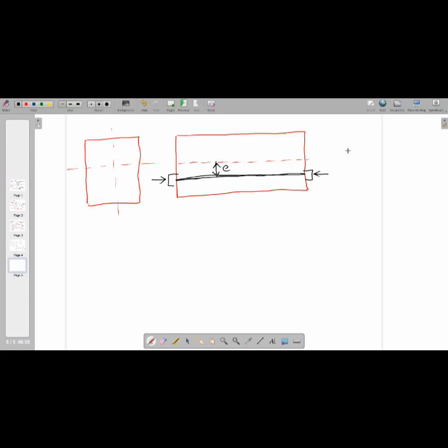Now see students, the stress distribution diagram for this will be uniform, P by A and P by A. There is a pre-stressing force here. What is moment? Moment is nothing but load into eccentricity. We can write PE, and bending stress can be written as PE upon Z. Usually at top it will be compression, so if I see here, you can write negative